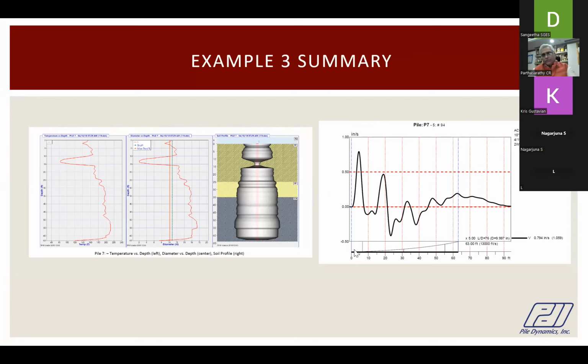So let me share with you some 2-3 case studies before I conclude in about 10 minutes time. Recently I was on a project which installed around maybe 1,500, 2,000 piles, in cohesion-less soil into weathered rocks. There was a basement for the project. It's a high-rise building. The top 6 meters were actually a dummy pile. These piles were installed without any casing or liner. Cohesion-less soil is very difficult to hold the borehole clean. And they installed the piles, all of them.